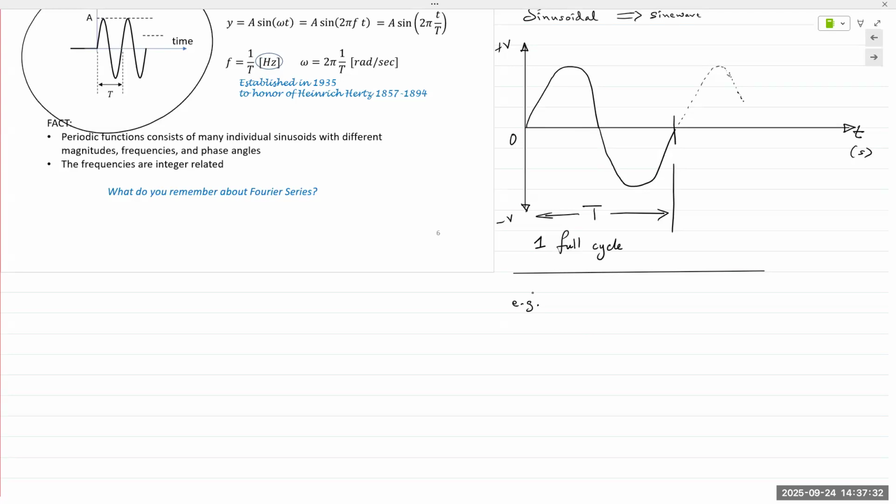Plus, you'd have to change the voltage from 110 volts to 220 volts. So electrical conversion will also be required. Not so much anymore. Nowadays, if you look at your laptop adapters, it will state AC in or AC input can be anywhere from 100 volts to 240 volts, 50 hertz to 60 hertz. North America is 120 volts and 60 hertz. Other parts of the world is 220, or let's say 240 volts and 50 hertz. Frequency does not matter as much, but the voltage does, and I'll explain why.